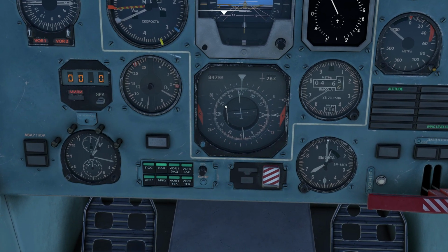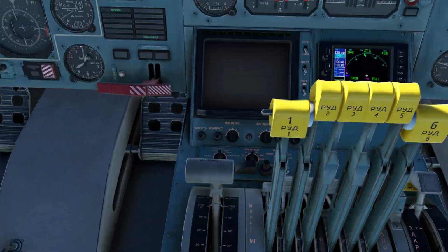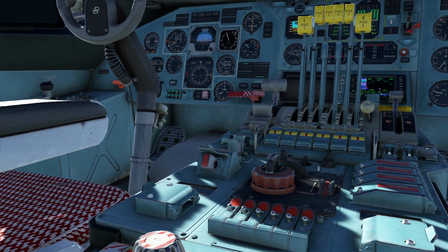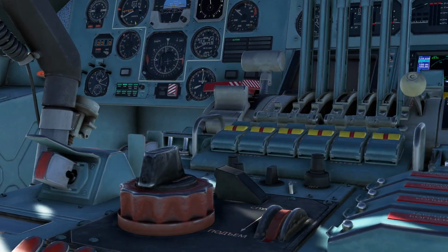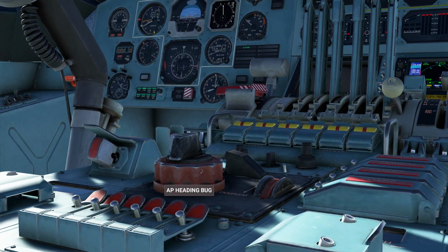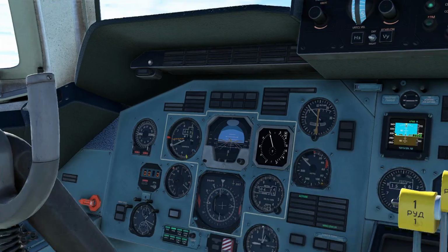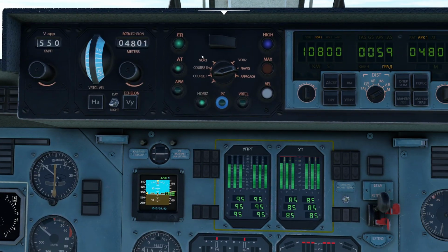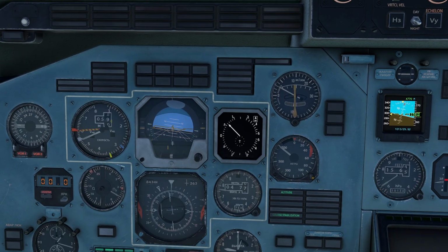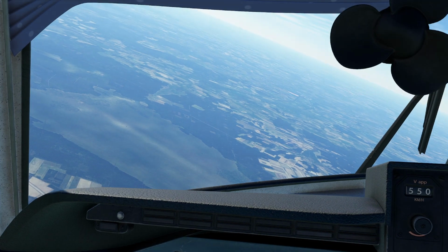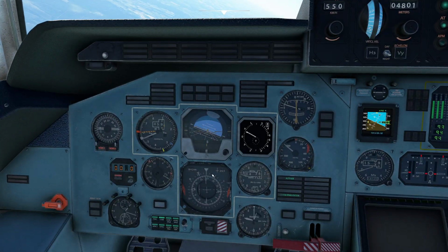I can see right now my navigation says I need to be about 240 here. So I'm going to come over here, and this is the trick that I've used for this aircraft, having been on other Russian planes, not unusual here. I'm going to come over to the heading bug, and you can see I can actually adjust the heading bug here. So I'm going to swing over to 240. Yeah, that's pretty good. Now, if you have external avionics that allows you to change that heading bug, it works the same way. With that all set, I'm now going to come over here and press the PC button. That's basically a course hold. So what's going to happen now is our aircraft is going to, oh, that's disorienting. It is going to execute a handy-dandy left turn onto 240.